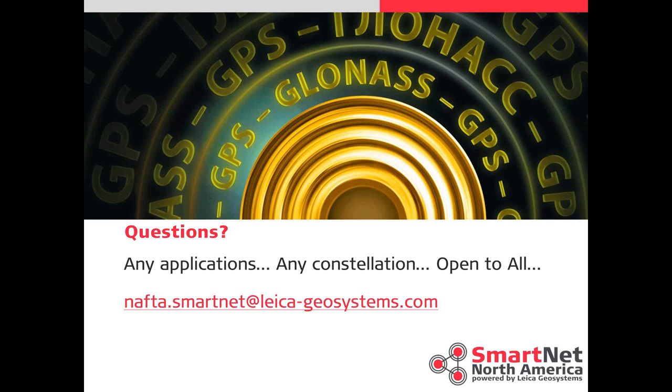Yes, the coordinates affect the corrections in that it's a weighted interpolation, so your distance from each auxiliary station does matter in computing the models for the distance-dependent corrections. I'm not sure what you mean by the second part of your question there, Shelby. If you want to shoot us an email offline or give me a shout directly, I can try to take that offline.